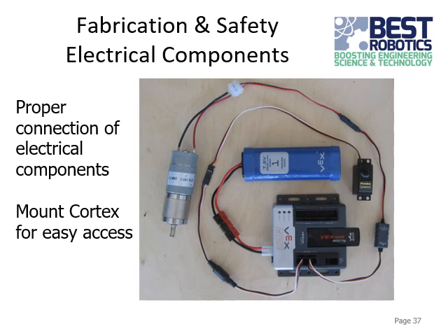Okay, onto some electrical components. Make sure everything is properly connected, first of all. I'd say make sure polarities are matched up correctly. That means red to red, black to black, that sort of thing. Also, make sure everything is secure in its connection, so it's not going to fall apart when it shakes a little bit or have an intermittent connection.